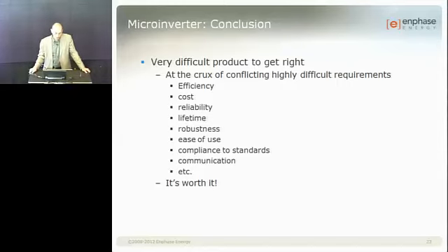My point of view on that, but I'm certainly biased, is that the only reason you would do this is because you don't know how to do a microinverter. Because the truth of the matter is that the string inverter is really what you want to eliminate, and it's still there. So sure, you can do conversion at a DC-DC point, and it's not very expensive, but you still have the string inverter, so you don't have any of the advantages. You still have high voltage DC, you still have a single point of failure, you still have the safety issue. It's always there. So it's really not solving the problem I think we should be solving.